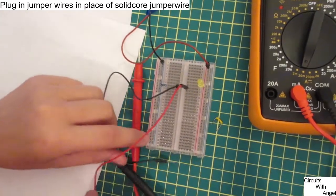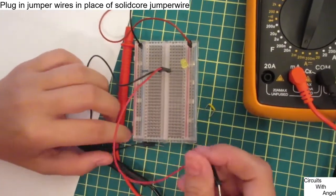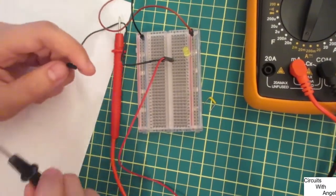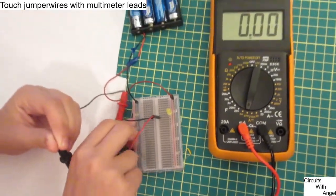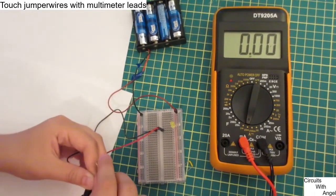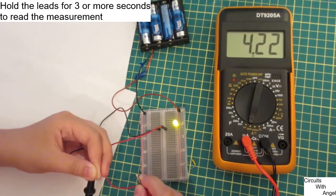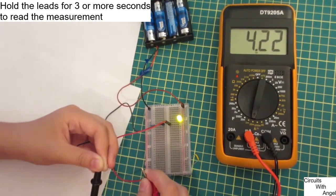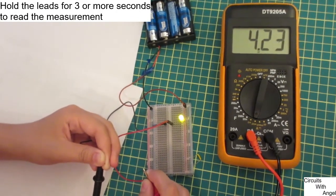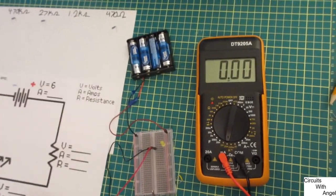And after we've done that, we can take our leads and touch them to the multimeter leads. Make sure your jump wires are connected to the components, otherwise you won't get a measurement when you touch the leads. When you touch your leads to the jump wire, make sure that you're holding onto it for 3 seconds or more. Otherwise, you won't get an accurate reading and your numbers will be all over the place. Alright, I'm pretty sure this is 4.2 milliamps.